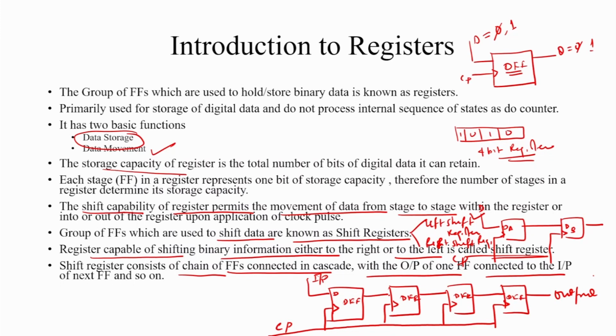So, this is known as a shift register, and this is known as a right shift register, because the bits are shifted in the right direction. When we make a left shift register, this is one register, this is another, all cascaded here, and the input is provided here to this D register. Whatever the output of this is, that is connected back to the input of the next. Similarly, the output of this is connected, and finally this is the output.